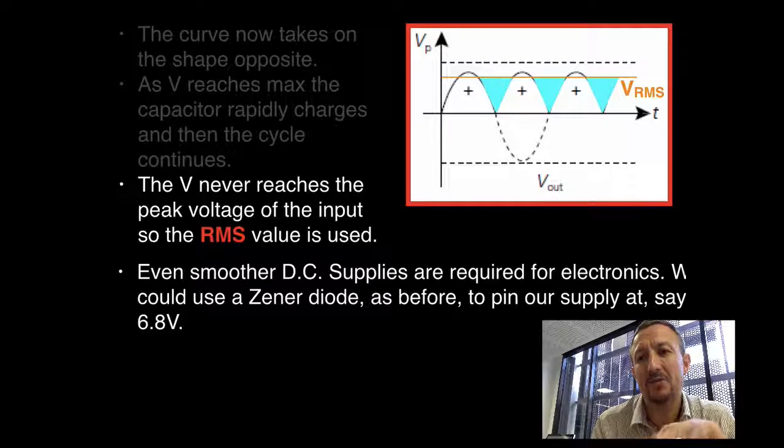So the capacitor smoothing allows us to fill in the energy gaps between those humps so that we get a constant supply of voltage, which is good for the appliance. So what the capacitor will continually do is it will continually charge and discharge as the AC current is beginning to drop, and then it will charge up as it's beginning to rise. So we get this continuous process.